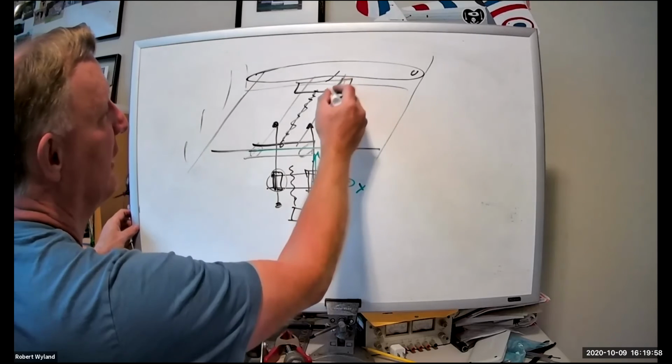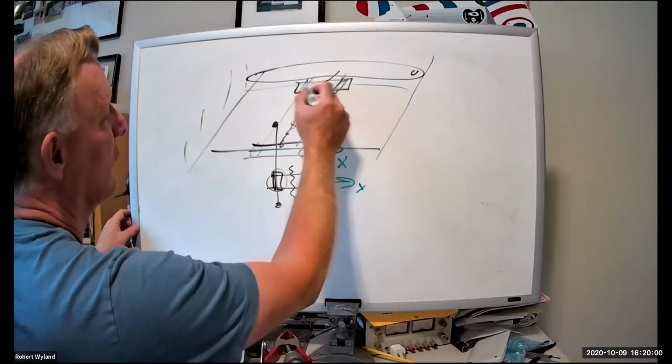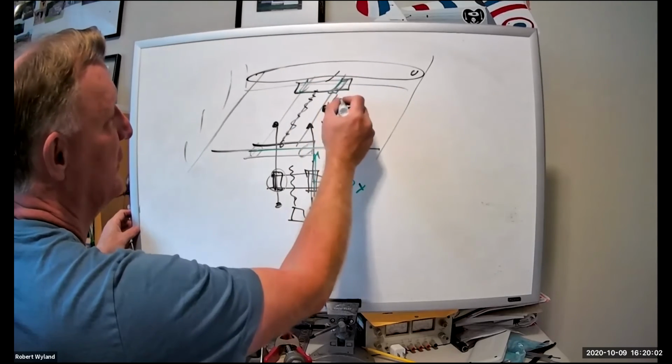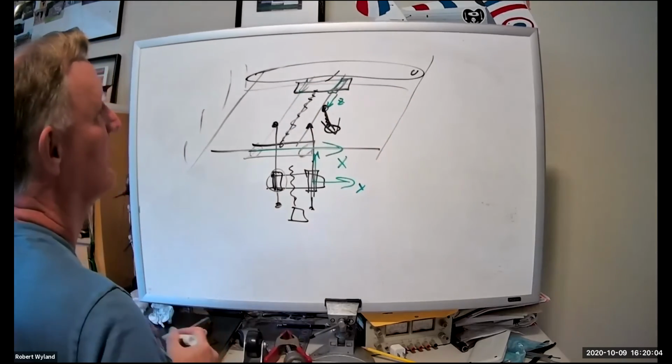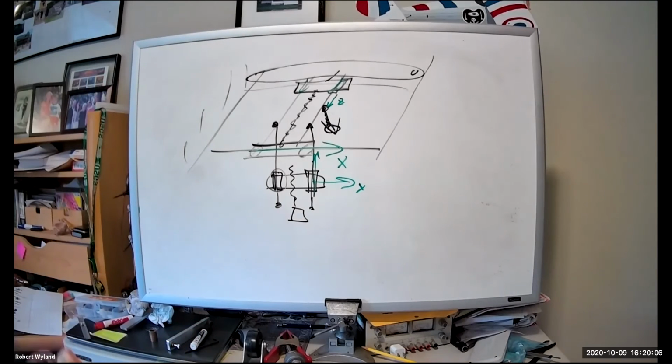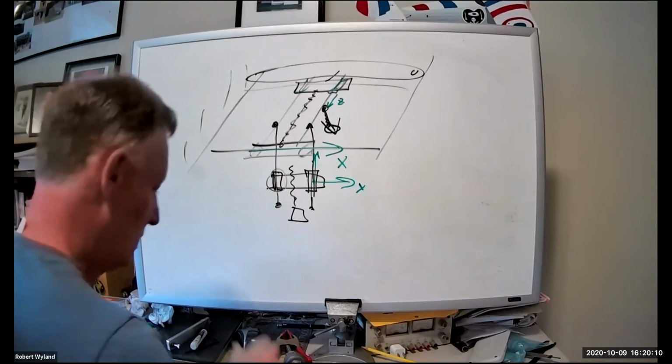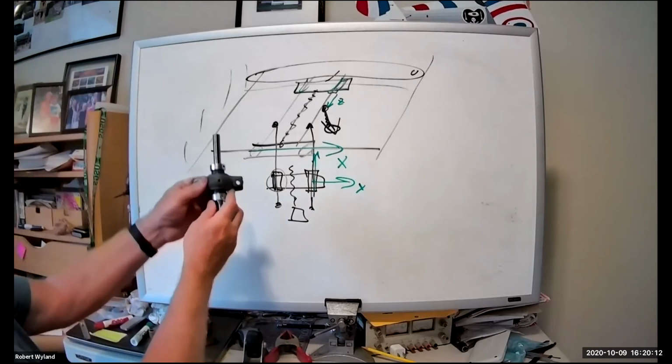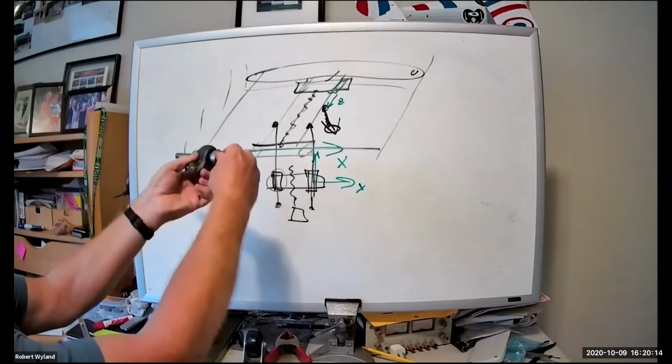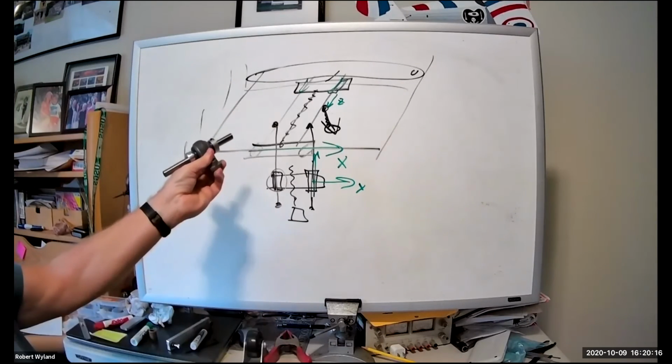And on this carriage here with more bearings, we're allowing it to slide in Z, but not the other two. So we're just taking the same bearing and basically orienting it in different ways.